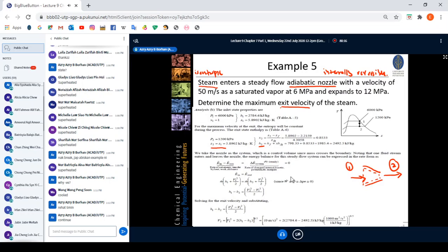Now, to get the exit velocity, that is the function of this diffuser, basically to increase the velocity at the outlet due to the change in cross-sectional area of the device itself. So from your energy balance for steady flow devices, guys, remember the long energy equation that you have, with the Q, W, and the mass flow rate for the inlet and outlet, and so on. From there, we know there is no W involvement. There's no W, there's no Q, and so on.